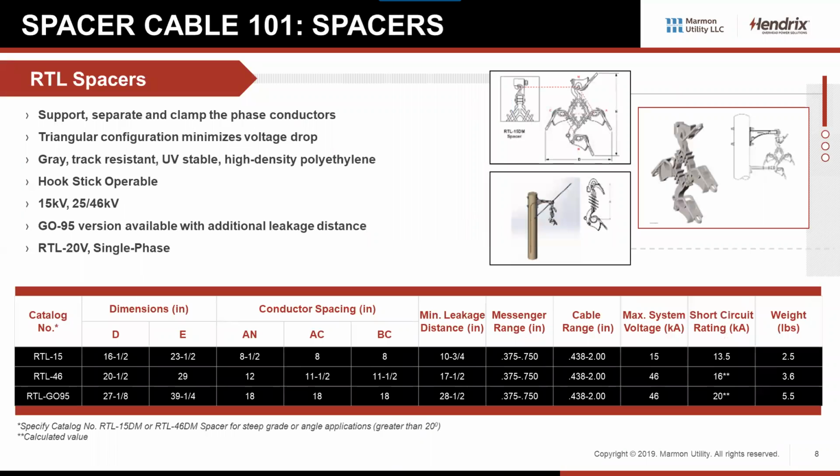The spacers themselves, since we're using all aluminum compact conductor, there's not a lot of mechanical strength there. So you can't pull it to any great deal of tension. So the phase conductors are really just kind of sitting slack, and the spacers are spread out about 30 feet from one another. So the phases aren't under any tension, and these are supporting the weight.